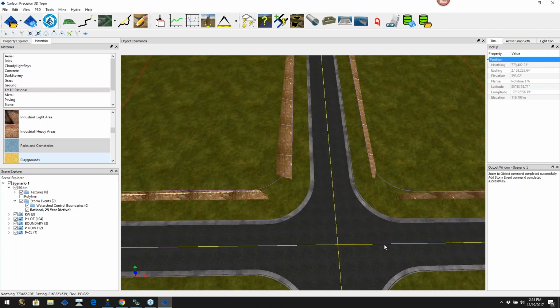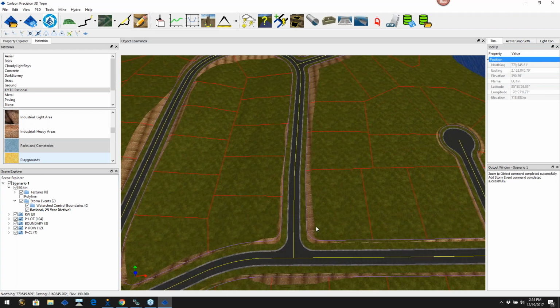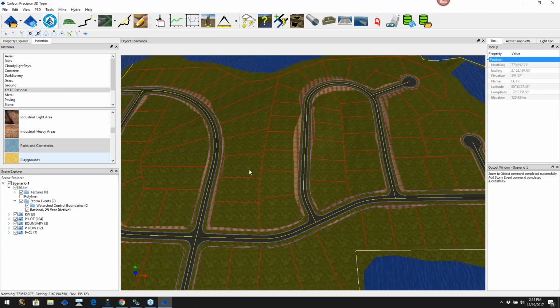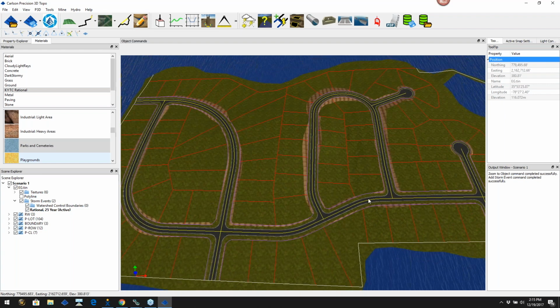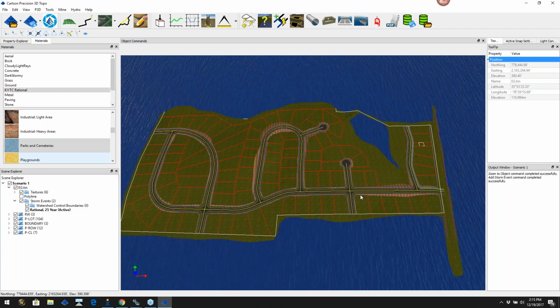So that's just different little things that are coming along. This will have a curve number, asphalt, concrete, whatever you have. If you have the footprint in here, you could say, okay, this is roofs, roofs inclined, roofs flat, whatever. So there you go. That's the surface when it's been merged. So we would end up with two, a pre and a post, for our calculation purposes.